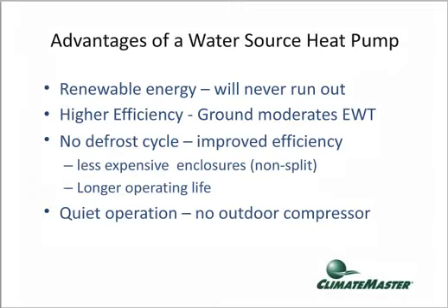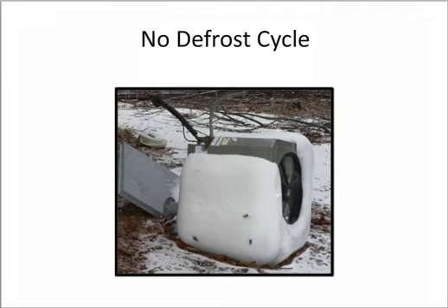The advantage of the water source heat pump, well, it's a renewable energy. You'll never outrun that well unless, well, you run out of water. High efficiency. That ground temperature, which obviously is influencing the temperature of your water coming out of that well, moderates the performance of that heat pump. We have no defrost cycle. We don't have outside units typically, especially with open loop. Longer operating life and quieter operation. Sometimes that's significant, depending on the location where you put it. And this fun little slide here shows what happens on an occasional abused and not really well maintained air-to-air heat pump when it starts to frost up.